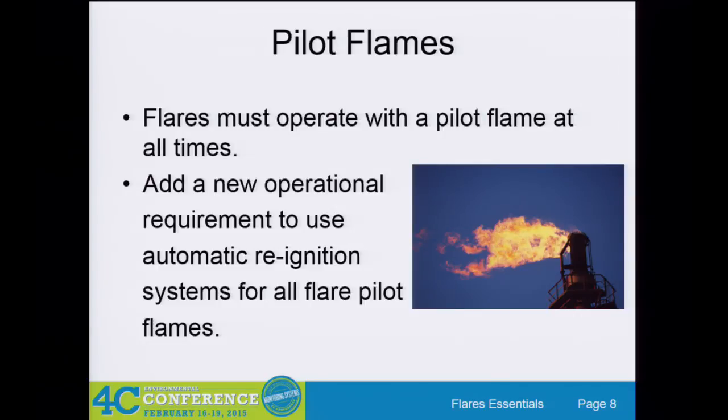For newer flare tips, you see pretty much standard now the high energy igniters on your pilots. So for newer flare tips, this isn't a big issue. A lot of your older ones, there's no HEI up there. You have the old style flame front generator, but those can be retrofitted, with the control panel down at ground level, to turn that into an automatic system. So it just takes some money, but it is a doable solution.